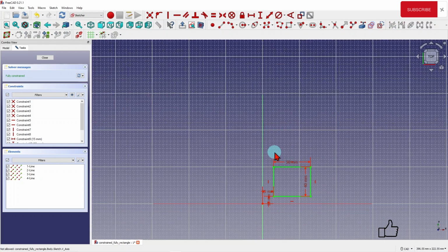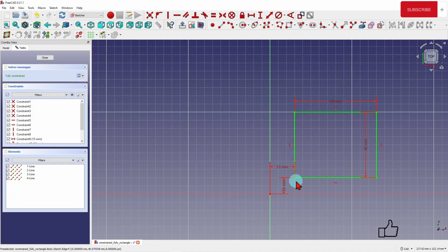Delete it here. So now here is the lock or the block constraint, and then you have the lock constraint here. Both have some advantages if you want to use them. Now, let's say having these two dimensions, I'm going to delete them. And now I can put a lock constraint.